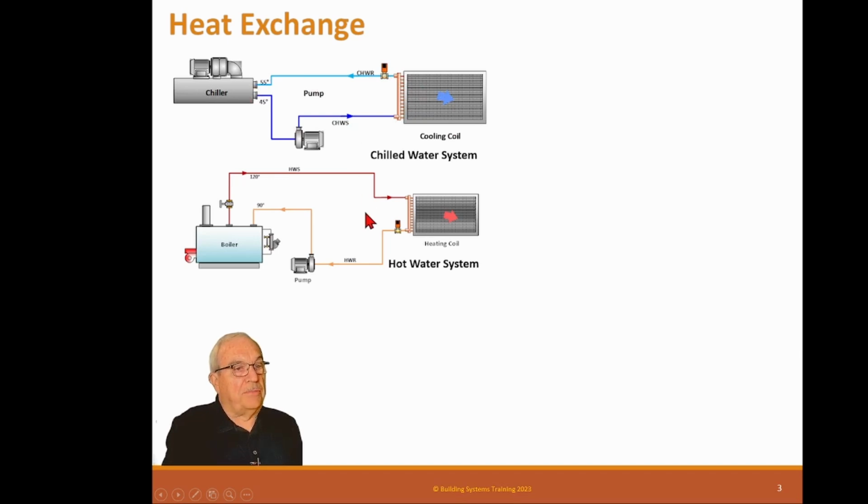The hot water system is similar, a little bit different. Instead of sucking from the boiler, the pump should push to it. Not always that way in design. The reason is that if you have 180 degree hot water, you're right near the flash point of the water. So if this is closed off and it's not taking any water for whatever reason, and you have hot water in here, it'll probably flash to steam and erode the impeller. It's really best practice to push through the boiler and push the hot water right out that way instead of having the pump up here. So that's the best way.